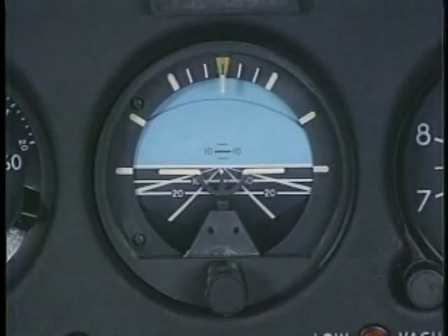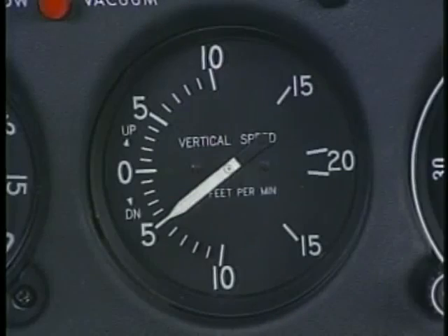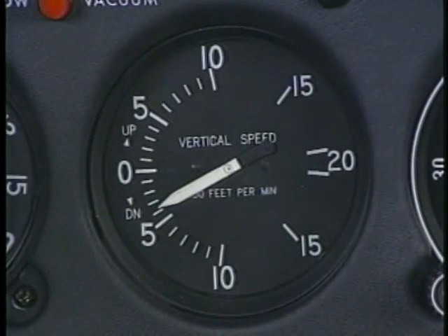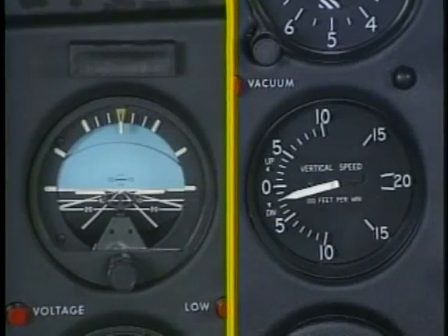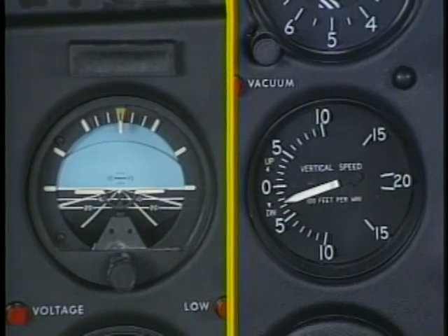Constant rate maneuvers are performed in a slightly different manner. In this case, the object of the maneuver is to establish a climb or descent at a constant rate. After establishing the approximate pitch and power settings using the attitude indicator and the throttle, verify the correct rate by referring to the vertical speed indicator. If a change occurs, you need to make an adjustment in the pitch attitude.